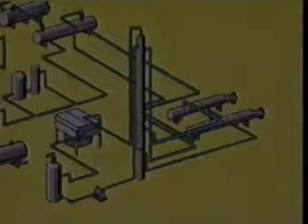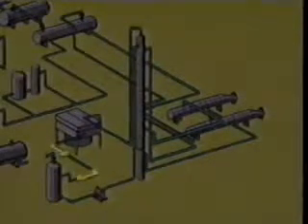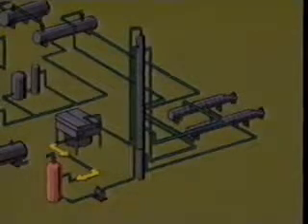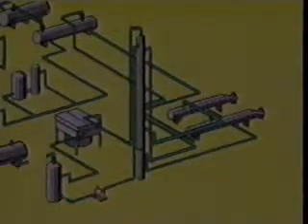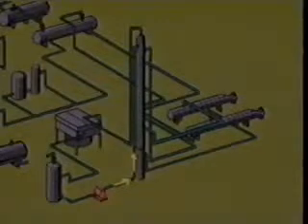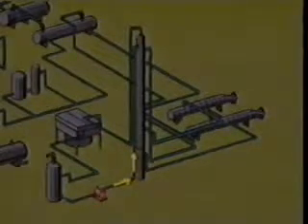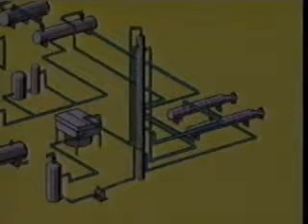Water and acid gases from the reflux condenser then flow to a reflux accumulator, where water is separated from acid gases. A reflux pump returns the water back to the stripper column for reflux. Depending on the amount of H2S present, acid gases from the accumulator may be sent either to a flare stack or to a sulfur recovery plant.